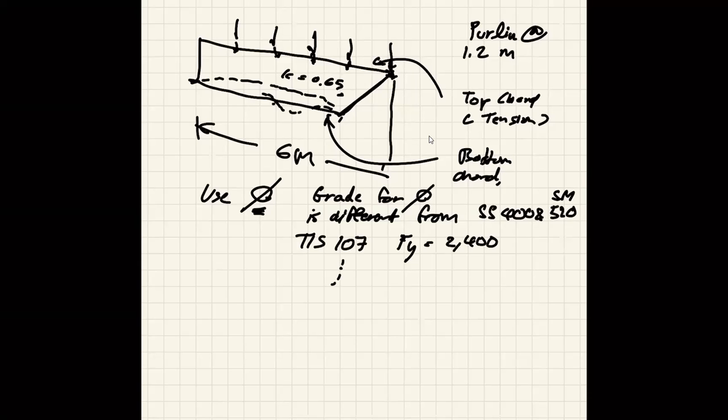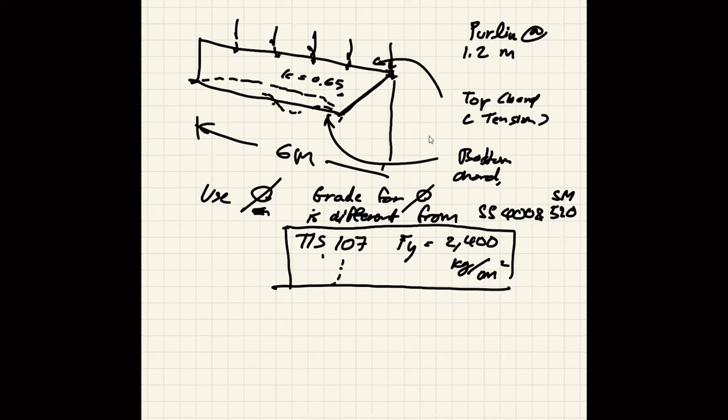Be careful that you use the right grade when you calculate. Okay. To use the wrong yield strength would be fatal. If you want to be an engineer and you don't know the materials you are going to use, that is unacceptable. Okay. So you only need to figure out the one critical unbraced length. Use that for your design. Come up with your member. Okay, so that is the end of the truss.